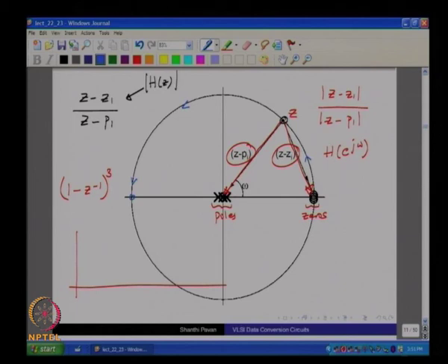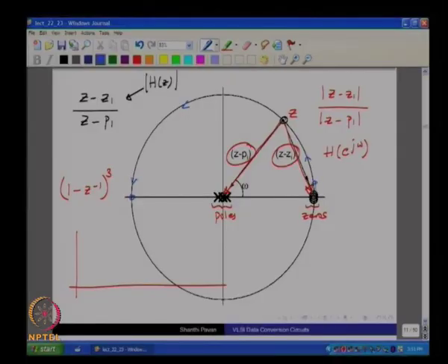Please note that wherever you are on the unit circle, the distance from that point to the poles always remains the same for this pole-zero constellation, so that remains 1. At DC, the distance to the zeros is 0, and then it starts to go as ω cubed, right. At ω equal to π, what do you get? Each vector becomes 2, so 2 the whole cube becomes 8.